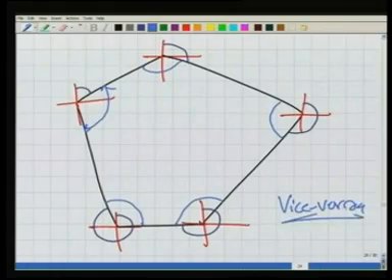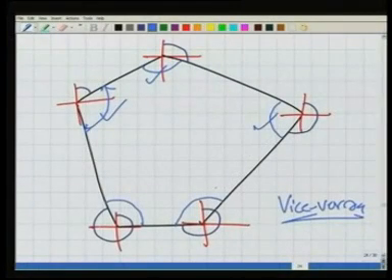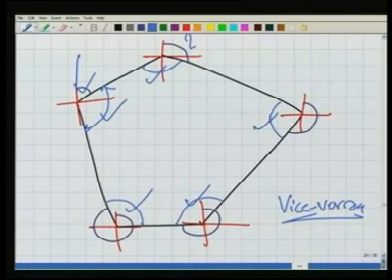If you know the internal angles of all the lines and the bearing of one line, let's say you know all these, and you know the bearing of one single line, then all these can be determined. Whatever system you want to, in WCB or QB, everything can be determined.